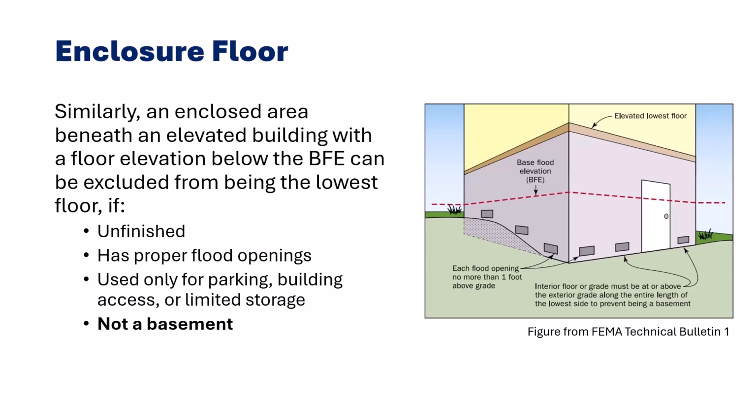And proper flood openings, remember, means at least 2 flood openings that provide at least 1 square inch of open area for each square foot of enclosed area. The flood openings have to be within 1 foot of grade. It's still the bottom floor, but then the next higher floor is the lowest floor for compliance purposes.